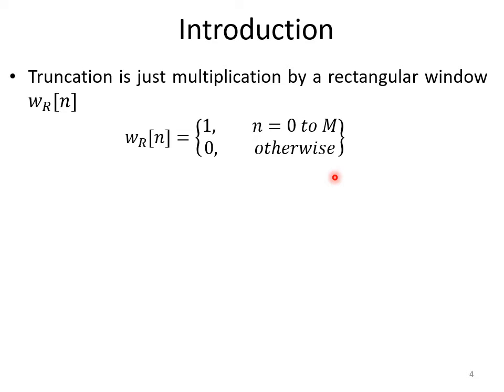So sometimes when the length of the filter is 21, we represent M equal to 21 in some books, and in some books when the length of the filter is 21, M is equal to 20, right. So here in this lecture we will assume that when the length of the filter is 21, M is equal to 20, right. So already one sample is deducted from M, right.